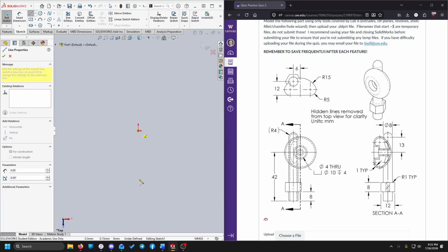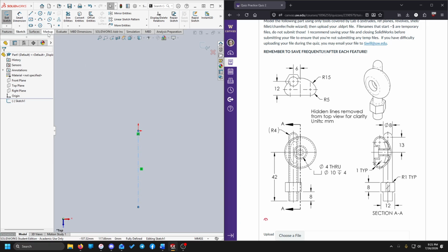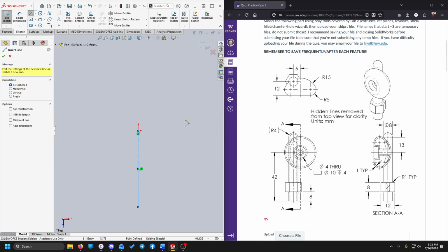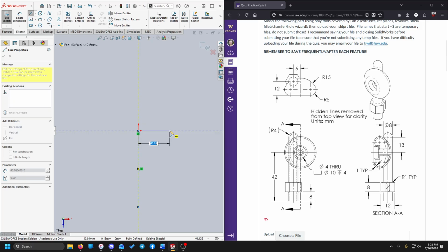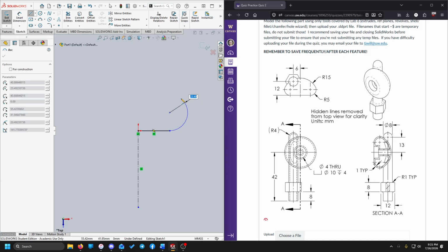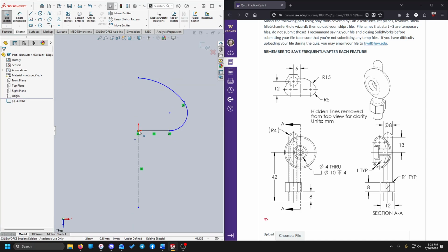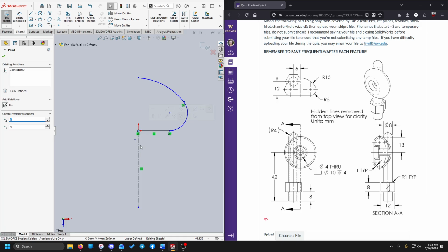I generally find it useful to do our center line first, just so that we've got something to work with. And then we've got a straight line down at the bottom. Use that auto transition tool that we covered earlier, bring the cursor back to the end of that arc, to the end of the line, and then back up, and then once more to get to right above our origin there. So we can select that endpoint, and one more line tool to close off our loop.